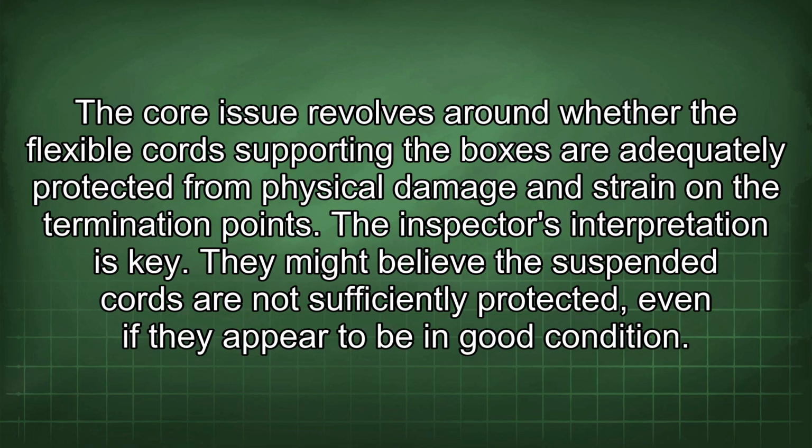The core issue revolves around whether the flexible cords supporting the boxes are adequately protected from physical damage and strain on the termination points. The inspector's interpretation is key. They might believe the suspended cords are not sufficiently protected, even if they appear to be in good condition.